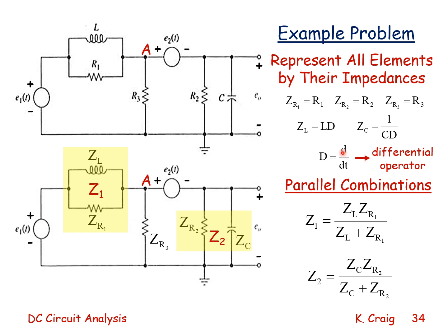So if I now use those values, or just leave the inductances in terms of Z, I have ZL and ZR1, ZR3, ZR2, and ZC. I note that ZL and ZR1 are in parallel. The parallel combination I define as Z1. I note that R2 and C are in parallel, so that parallel combination of impedances I call Z2.